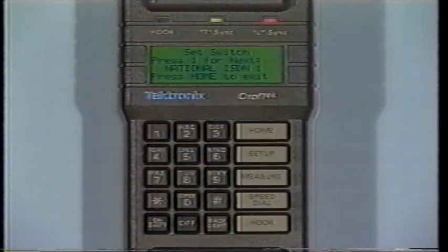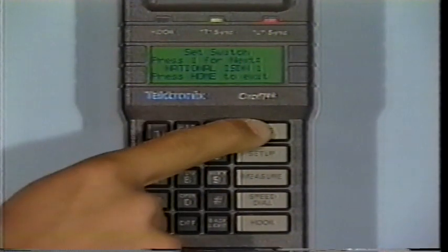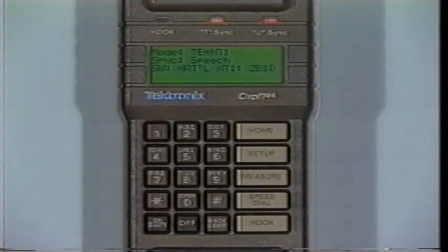Note that the National ISDN protocol can be implemented on any switch, AT&T's 5ESS, Northern Telecom's DMS, or Siemens switches. It is switch independent, so if you are on a national ISDN line, then the switch type that you will want to select is National ISDN-1. If you are on a 5ESS or DMS custom line, then you should select that particular switch type. When you have made your selection, press the Home key or the Setup key to exit. The switch type you selected appears on the home screen.